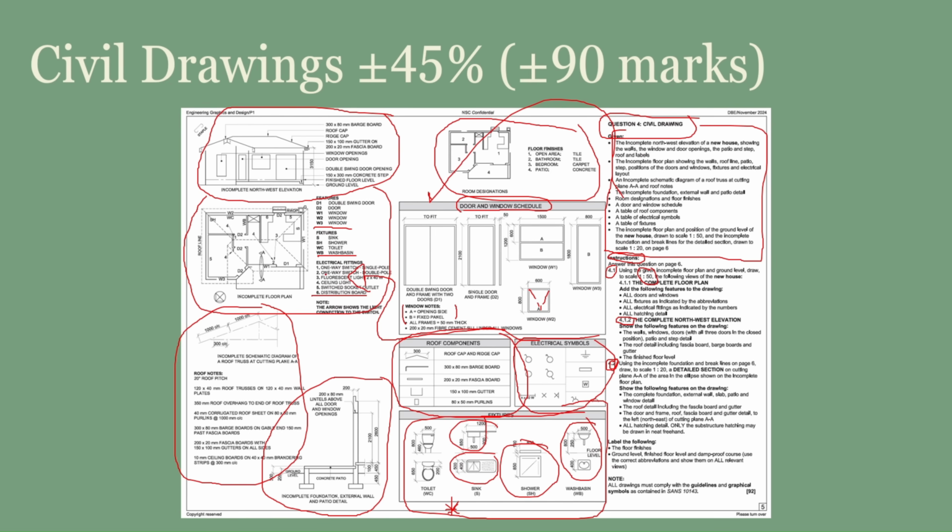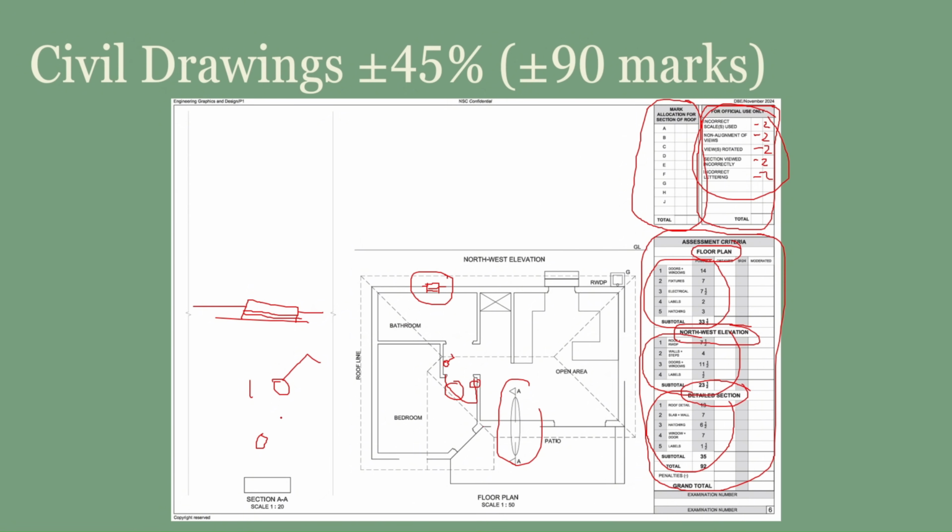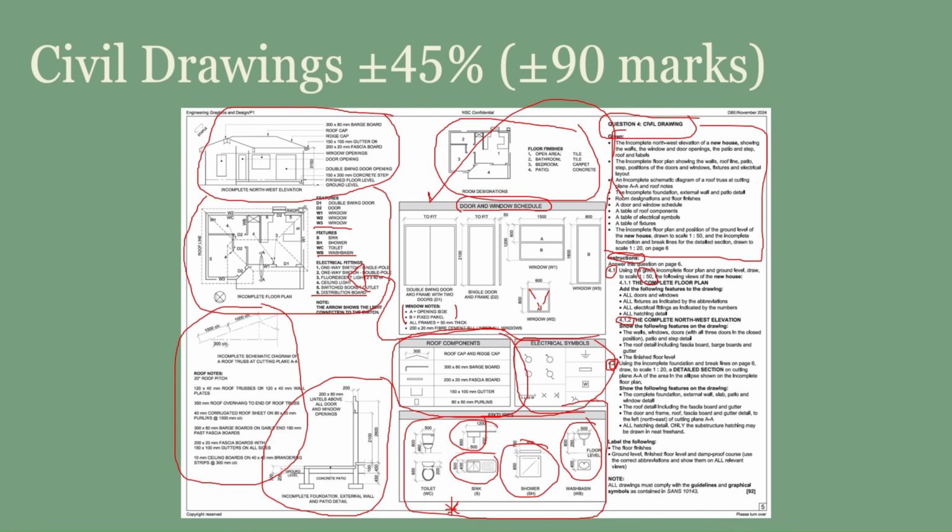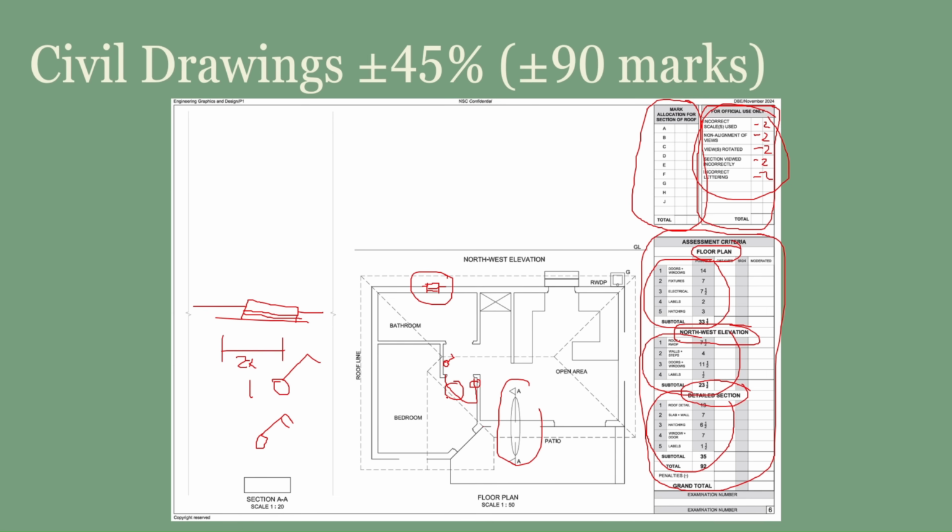Then you'll continue to number 2, which is your one-way switch double pole. You know that the one-way switch double pole is a circle with 2 ears. So you'll put that on all the 2s. When it comes to a fluorescent light, make sure that you put in whatever they say. It's either going to be 2 times 40 watt or 2 times 80 watt or 2 times something, or it's only a 1. But they will specify it there for you on the fluorescent light. That is additional information that you need to put on the fluorescent symbol wherever you need to put it in. Usually fluorescent lights are put in a kitchen or in a garage. And then I will put there 2 times 40 like they have stated there.